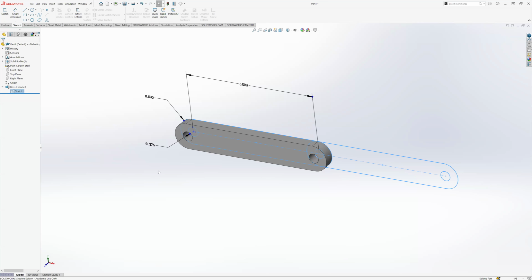Typically it's not necessarily going to take longer just because it's an assembly, but if you've got a lot of parts and especially contacts, contact conditions will definitely take long. Especially when you're dealing with contacts like non-penetration or just a contact condition, it can be very long for SolidWorks Simulation to analyze those, because it has to figure out how every body interacts with every other body that's touching. So those can definitely be longer. When you're dealing with multiple parts, especially with contacts in an assembly, those are usually expected to be the longer types of simulations, if that makes sense.